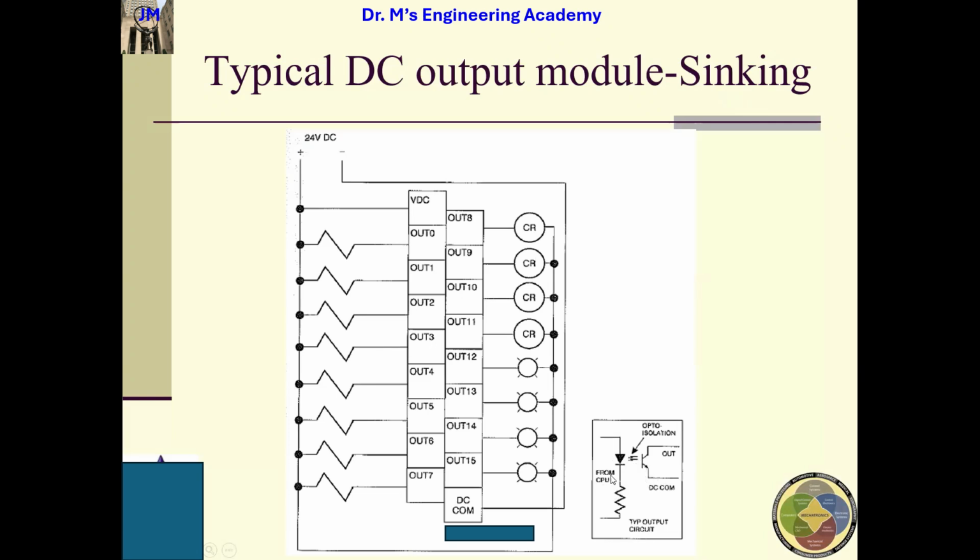If I have a signal here, this signal will be conveyed to the output actuator using light instead of being physically connected. If we were physically connected and we had a voltage disruption from outside, it would go to the CPU immediately and burn it. Right?